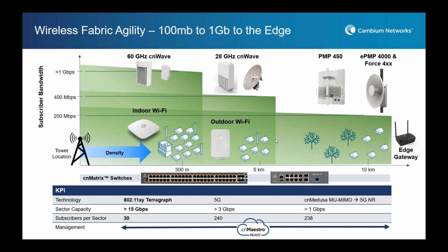There's another question here about putting equipment and power supplies at a home that is a mesh node site. So I think we see service providers doing this in different ways. So effectively, when you look at those distributed mesh architectures, one approach is to put the distribution node on one of the homes that you're serving. So we call that a donor home. And in that case, you can either put a power supply on the accessible power supply on the outside of the house. You can also do a traditional PoE injector inside the house. And then it's kind of up to the service provider how much battery backup they'd like to apply to that in that particular approach.